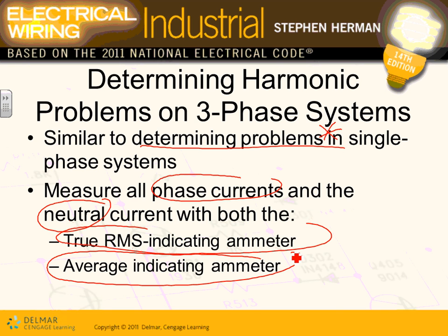So most of bigger buildings, guys, they don't even use this method. They use circuit breakers like this that monitor the system and tell you not only that you have a problem, but also what harmonic. Is it the second harmonic, the third, the fourth, and how much? It's not enough to tell me I have a harmonic problem, but how much and which one is the offender? Is it the third harmonic, the fourth harmonic, the fifth, the ninth? Because if you know which one of them and how much, if it's small, who cares?